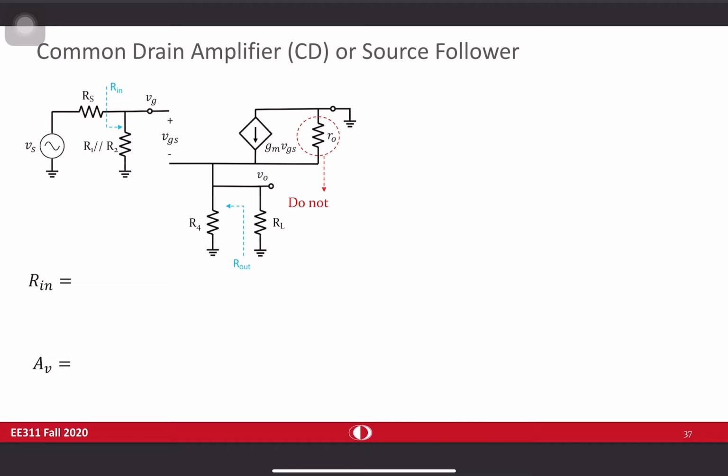And as you see, the most critical thing: put the transistor port names first. Drain is AC-wise grounded, and there was R3, and R3 was shorted by means of C2. What we have is R1 and R2 in parallel. C1 is shorted in here, and at the output C3 is shorted, so we end up with this circuit.